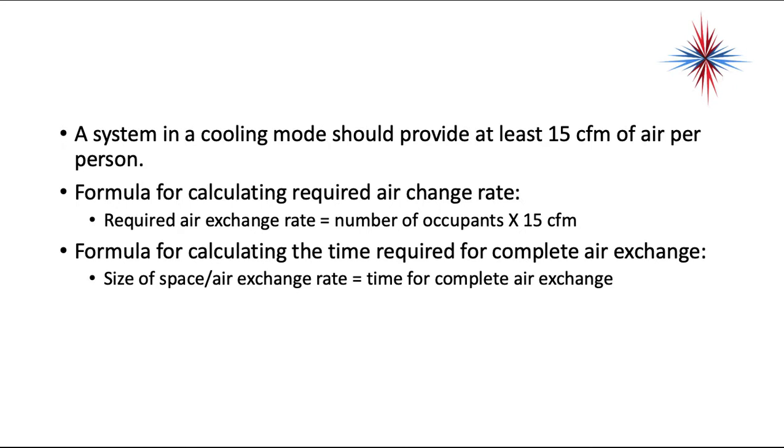Okay, the formula for calculating required air exchange is actually relatively simple. The required air exchange rate is the number of occupants times 15 CFM. The formula for calculating the time required for the complete air exchange is the size of space divided by the air exchange rate, and that will give you the time for complete air exchange. And again, size of space is volume, so it's in cubic feet.